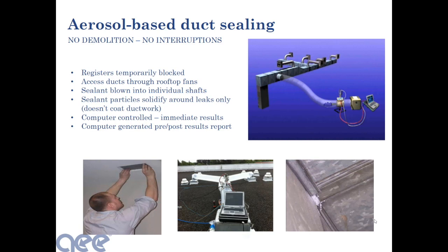Then they would create an aerosol. In the Lawrence Berkeley National Laboratories, they envisioned this aerosol to be something safe and benign. In fact, they used a vinyl acetate product that was a base for chewing gum and babies' pacifiers and latex paints and hairsprays, something that was very benign but inherently very elastic. Turned it into an aerosol and pushed it through the duct system.